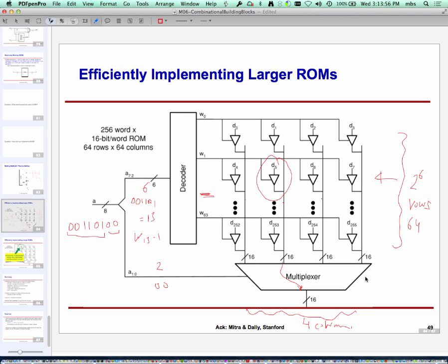In this particular case, D0, D1, D2, D3 are okay. Yeah, you're right, they're 16-bit each. So our memory is 16-bit wide. D0 is 16 bits of data. D0 would be some number like 0011010111110101, 16 bits. It would be something like that. And these wires that you are seeing running are 16-bit wide, so they are really 16 wires running.